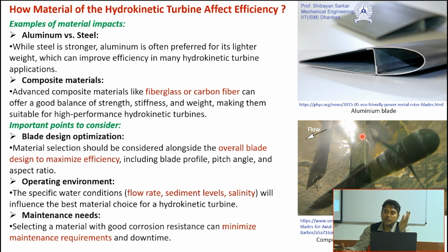You have to analyze that data for water quality, for sediment, as well as the reliability of getting water flow throughout the year, even throughout the day, and for which purpose you are installing this energy generation system. That means whether you wish to provide electricity for peak time, or for base load. That will be very important when you are cross-checking the reliability of getting a certain amount of water in a particular river.